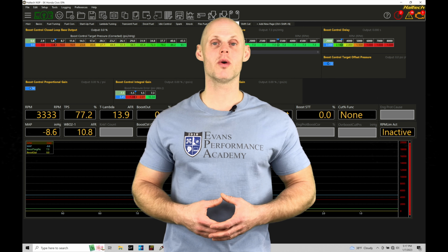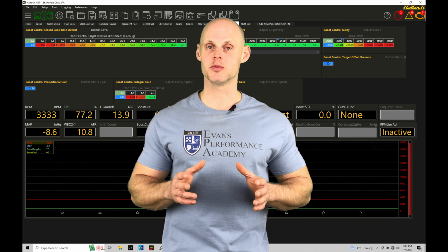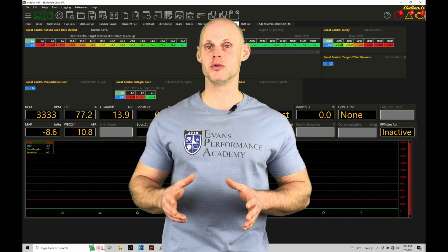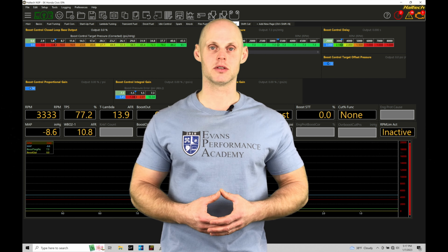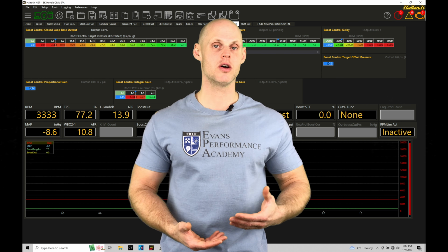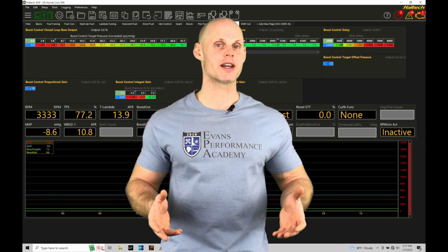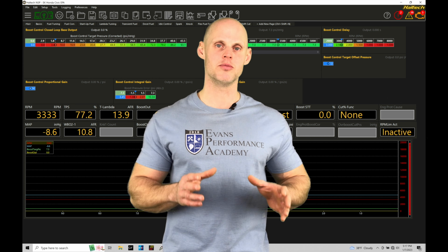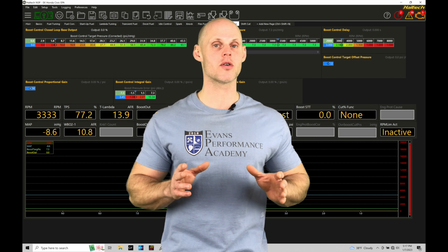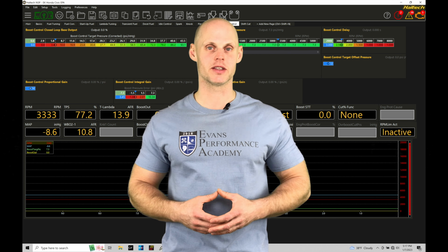In this training tutorial, we're going to take a look at programming open loop style boost control. Open loop boost control is the most simplistic way that we can work within the boost control tuning. This allows us to just input a basic duty cycle and get some type of a response in our boost. We should see the boost rise as we raise our duty cycle. There's all kinds of strategies and tips and tricks within the boost control just for open loops, and we're going to cover all of that here in this training module. Without further wait, let's jump in so we can check this out.